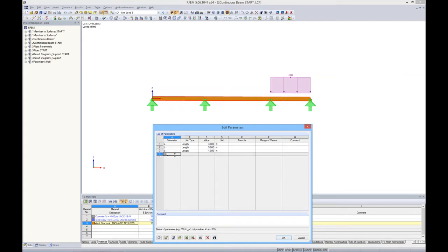Now let's say we also want to consider dead load. Now instead of length here, I actually want to go down, and this is where I told you before there's quite a list to choose from for the amount of parameters you can actually define. Precambers, moments, stresses, time, mass, percent. So we have quite a powerful option here when it comes to parameters. For this case, I'm just going to go for a line force, and I will go ahead and do -4 kilonewtons per meter, and maybe my live load, again a line force, and I want to do -2.